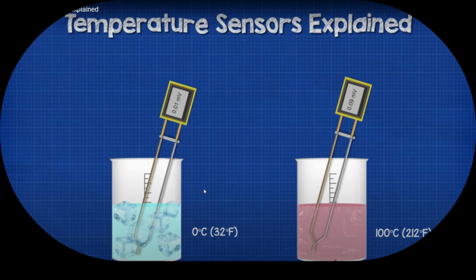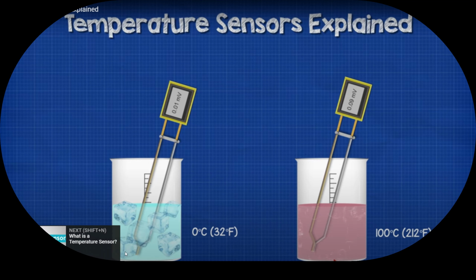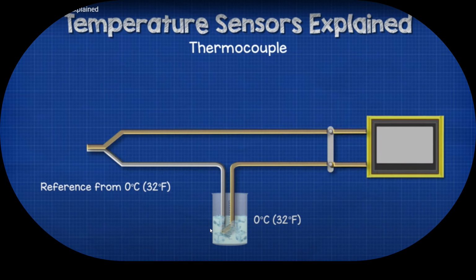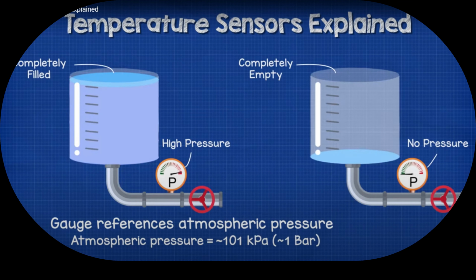Of course, to measure the thermocouple relation between the voltage changes and the heat effects at this junction, we need to give them some reference. So we need to return it back to a certain reference, for example the freezing point or the melting point of water. We can depend on this reference, and our millivoltage changes are based on this reference in the voltage and the temperature.